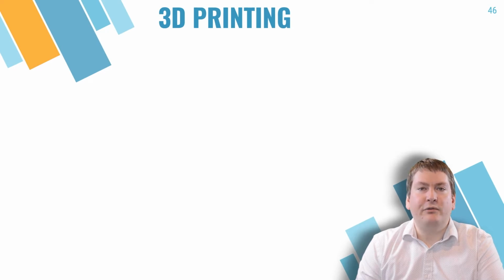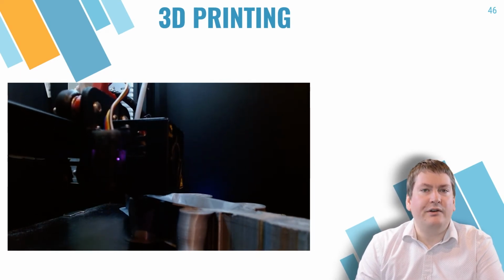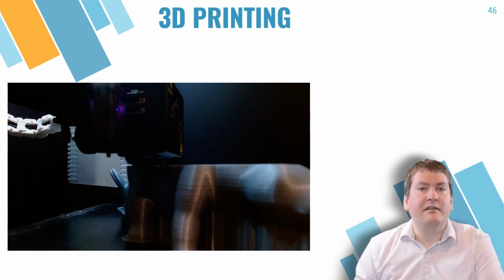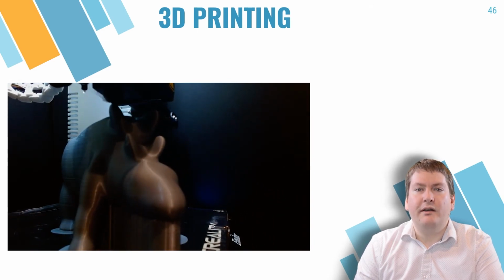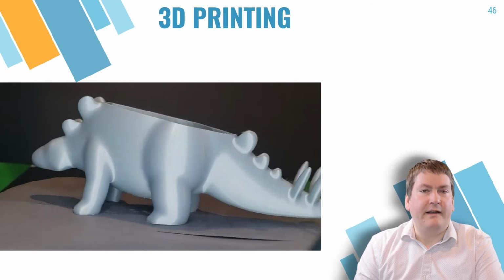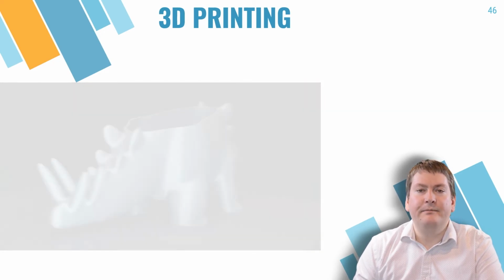So now that we have seen a 3D printer in action, what can they be used for? Well, by far the most common and accepted use is in prototyping and research and development. When you're developing a product for the first time, particularly one with plastic parts or casing, it can be cost prohibitive to make a mold for each iteration of the product's design. Rather, you only want to make a finished mold once you are sure the product is ready. 3D printing allows product designers and engineers to rapidly create prototypes in a cost-effective way during product development, and only commit to molds and manufacturing equipment once the product is finalized.